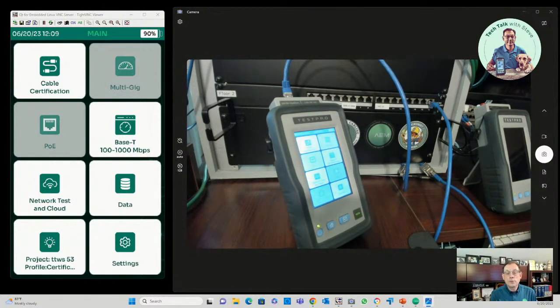switch or router, a work group hub. Those devices have built-in grounding through their electrical connection, and you should use a shielded cable to go from the telecommunications outlet shielded jack to the equipment, which has a shielded jack built in. That is where the grounding takes place. That is the grounding at the remote end. So that's how you ground. You don't ground at the telecommunications outlet itself. It's grounded through a shielded patch cord.